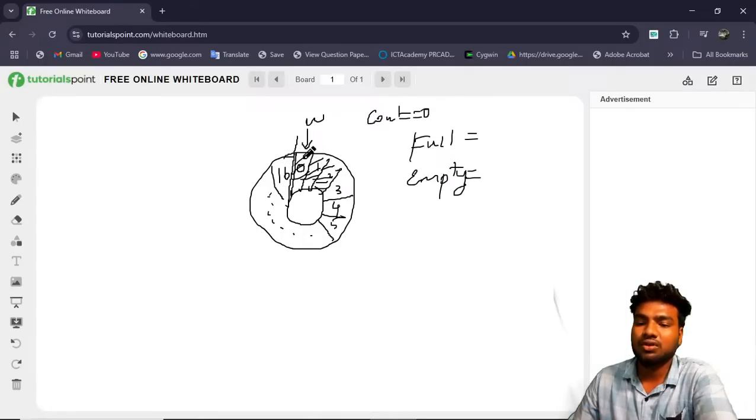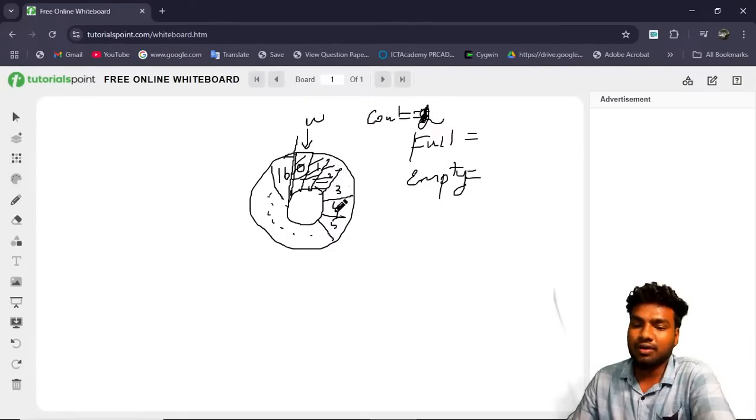After the first location is written, the count moves to 1, and then to the second location, and the count increases. In the third location my count also increases. Every time I write a new location, I increase my count. If I write all 16 memory locations, my count will be 16. If count equals 16, then my FIFO memory is full.